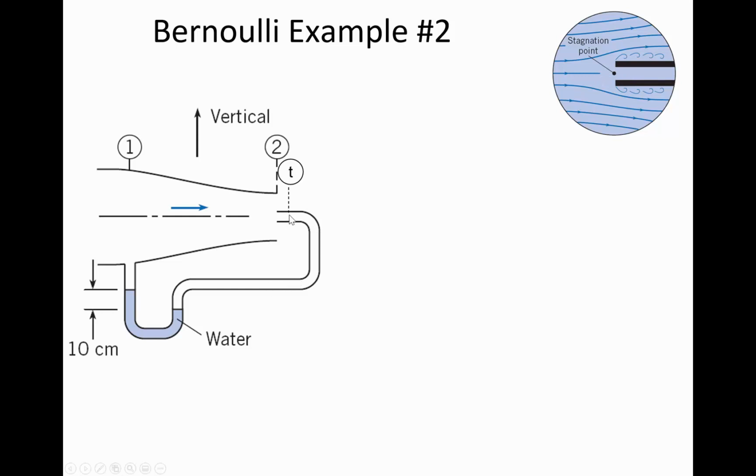The air isn't flowing in the tube, it is stopped, it's stationary. Static conditions means that as soon as we turn on the wind through this nozzle, it causes the deflection and then it stops moving. It's not like the water is going to keep flowing until it goes into the nozzle. It's in equilibrium after a certain velocity has been achieved, and then the water stops moving and the air inside the manometer is also stationary.